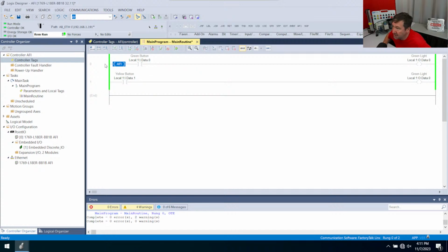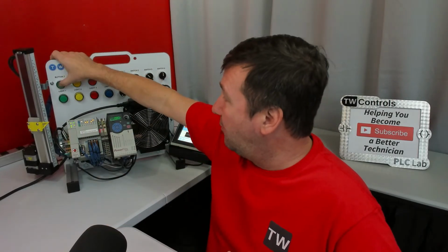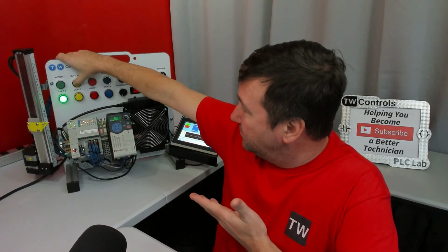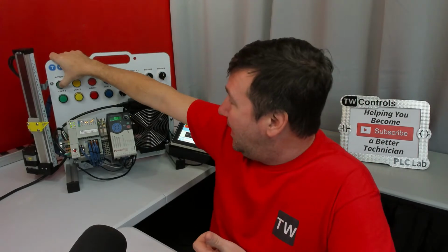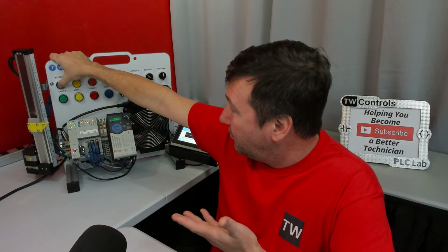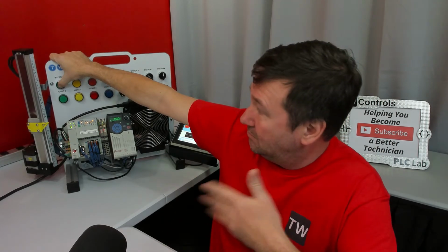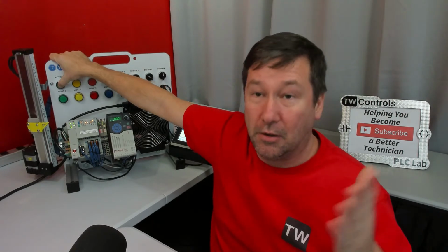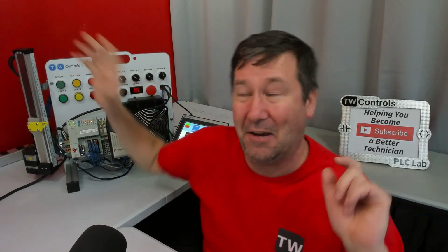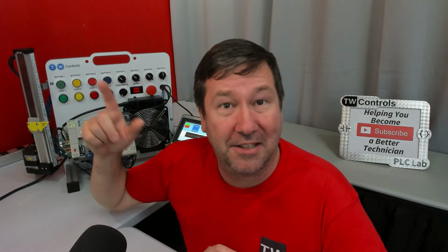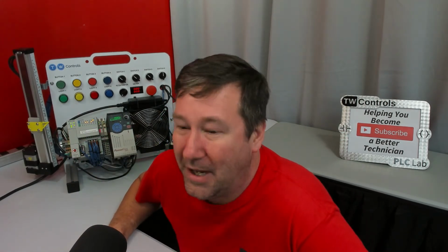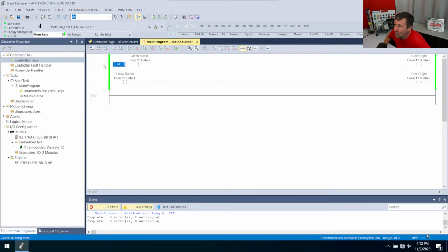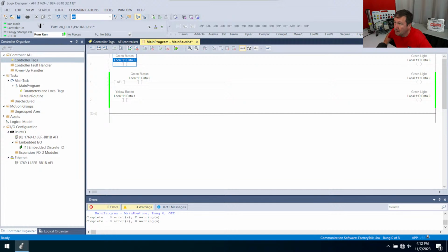And this is where the whole discussion started, that no, this doesn't disable the rung. This just makes it false. And that's why now we press the button, occasionally you see it flicker. And if we press the green button, while it seems off, occasionally, of course, it's not going to do it when you're staring at it. Well, you can go back and watch that video. Occasionally, that was coming on. But okay, now let's talk about, oops, no, I'm sorry. I got the wrong code in there for that. That was another one. Okay, but so then we talked through how we could truly disable a rung by adding a rung above and below it.